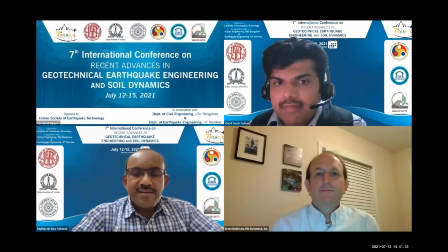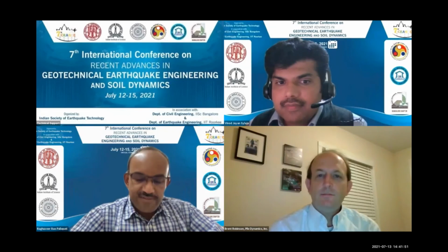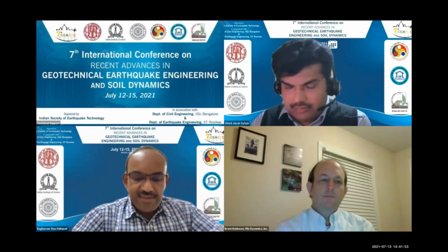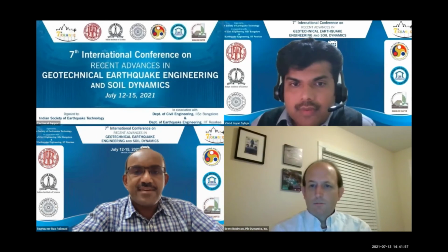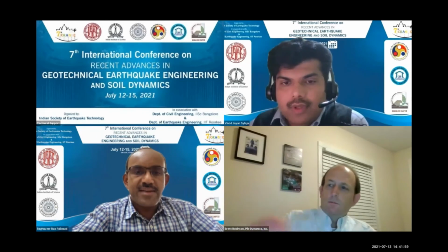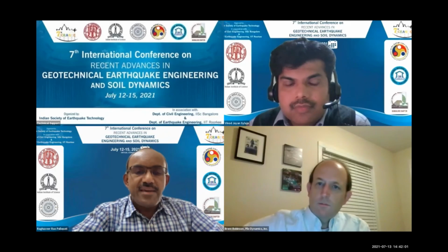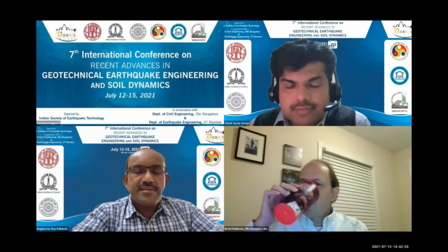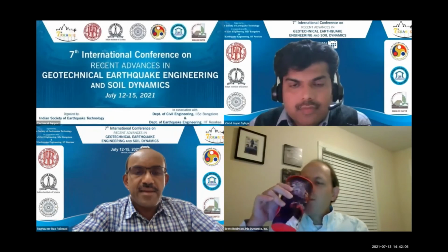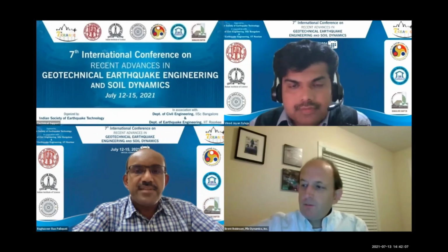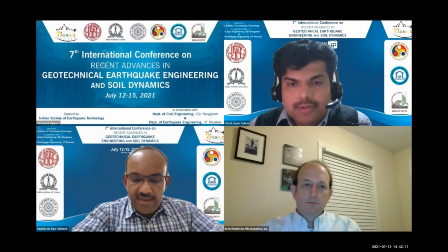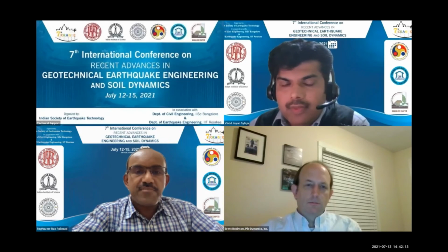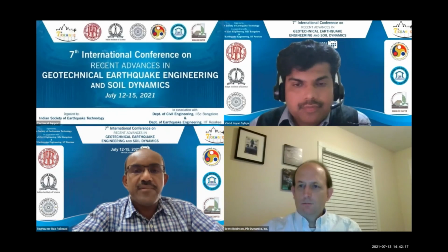Thank you, Professor Vinod. Very interesting presentation. But there is a serious limitation compared to synthetic material, because coir has a limited lifetime. Even all the laboratory testing results are applicable only at the time of installation, but with time they degrade. Whenever this degradation takes place, the improvements we are expecting should occur before the degradation.